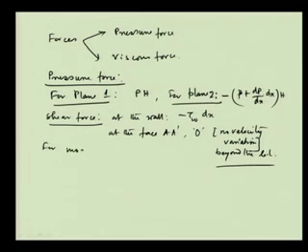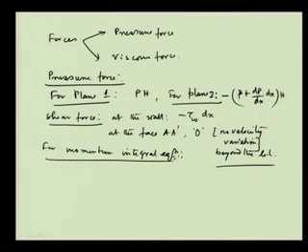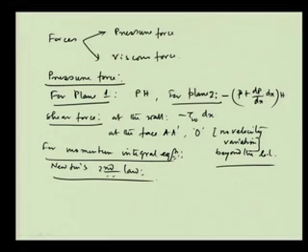Then, if we apply the momentum integral equation, and apply Newton's second law, it says that the applied forces give the rate of change of momentum in the control volume, which is the control volume we have discussed. So the applied forces are minus tau_w minus dP/dx into H, taking the pressure and counter pressure at points 1 and 2.